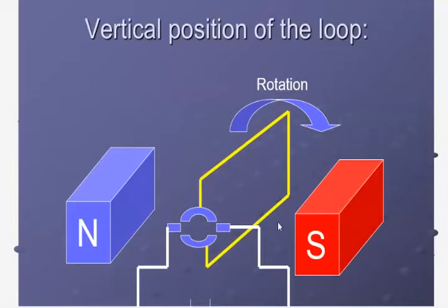And now come to the point. Here current is along this direction. So you just place middle finger along this length and forefinger from north to south. Then your thumb will be pointed downwards. So again, these two forces are collinear. Therefore, their rotational effect is 0. Their rotational effect is 0 and their vector sum is also 0.